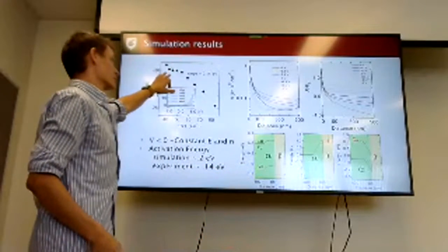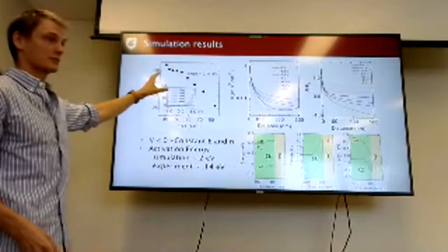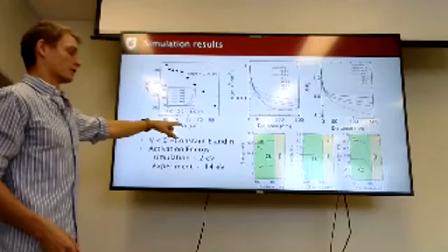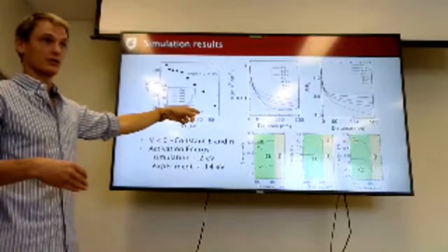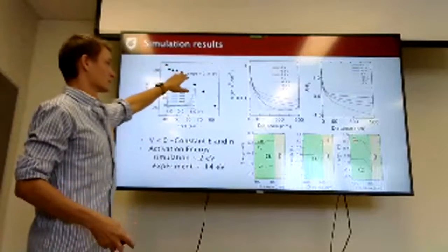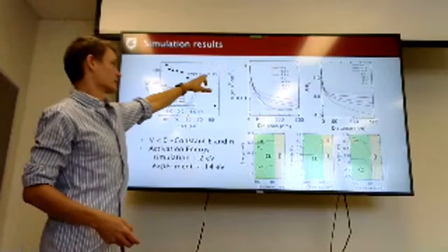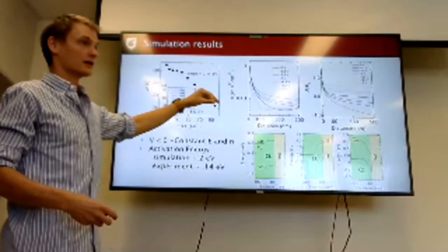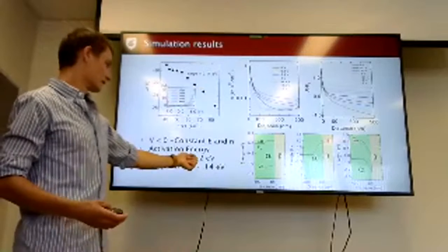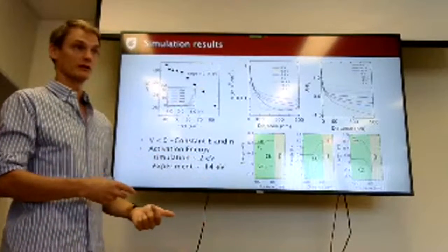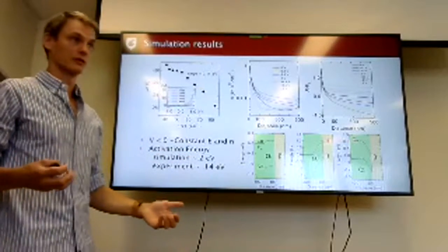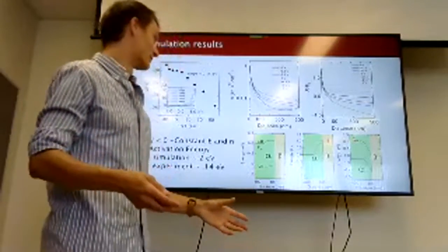The thermal barrier we can find by making an Arrhenius plot of the natural log of current versus beta, 1 over temperature. We get this straight line here, which is a strong indication that there's a thermal process going on. The slope of this straight line is 0.14 eV, and the simulation says the thermal barrier is 0.2 eV, which is pretty remarkable agreement between theory and experiment.